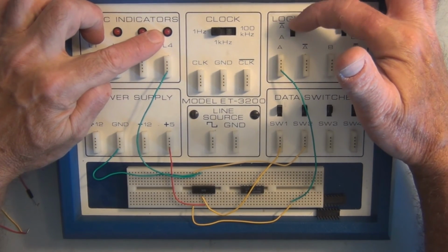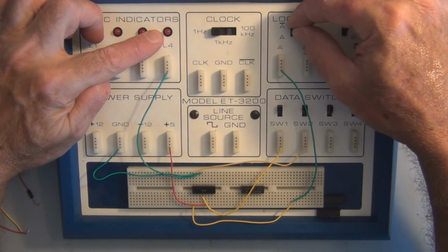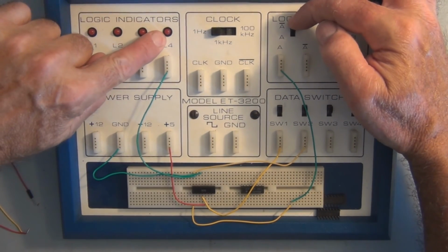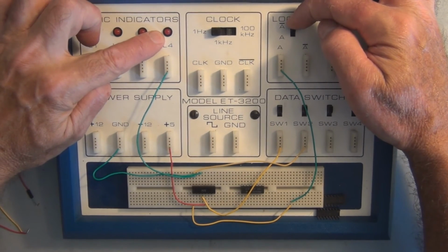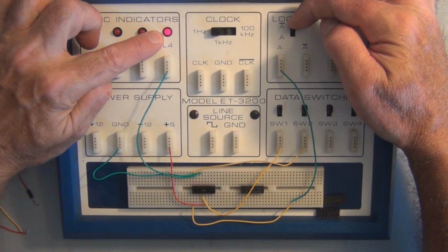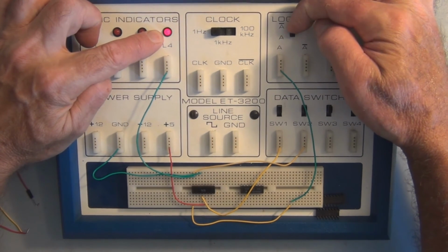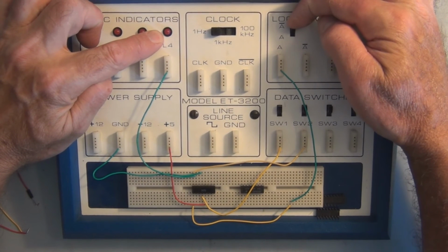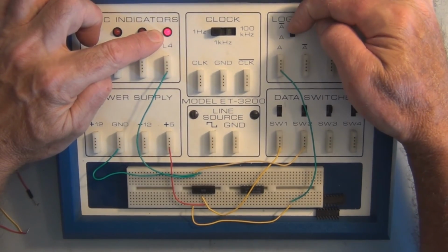So I'm manually being a clock signal here. So here we have a 0, so the next falling edge of the clock, this should go to 1. And then on the next falling edge of a clock, it should go to 0. So here we're in the toggle mode of operation with J equal to 1 and K equal to 1.